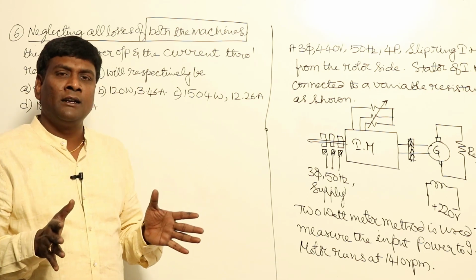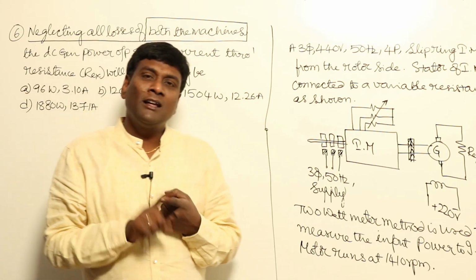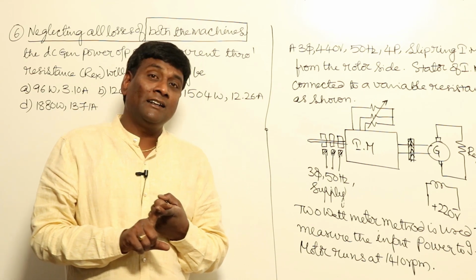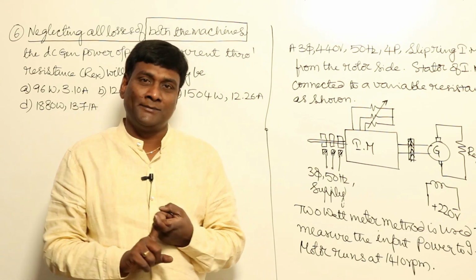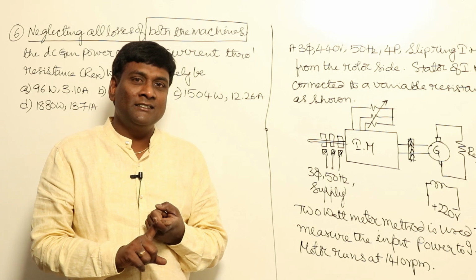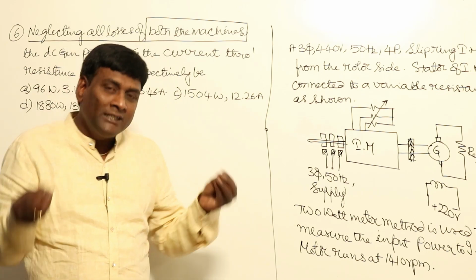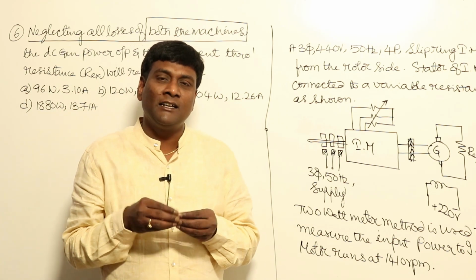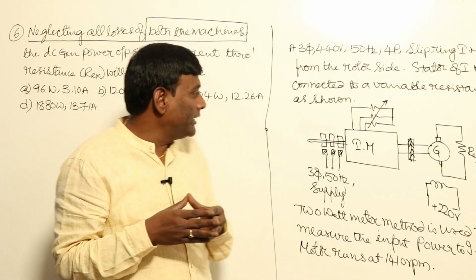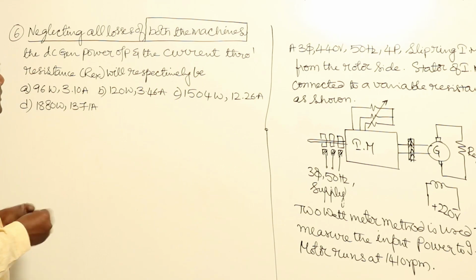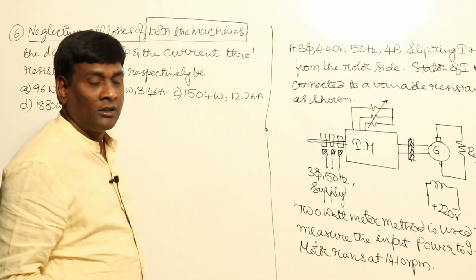We clearly said that if rotor resistance is not considered, the torque angle delta is going to be 180 degrees. If resistance is considered and reactance is not considered, delta will be 90 degrees. If both resistance and reactance are considered, delta will be more than 90. So the point here is very simple: we cannot neglect the losses of the rotor.